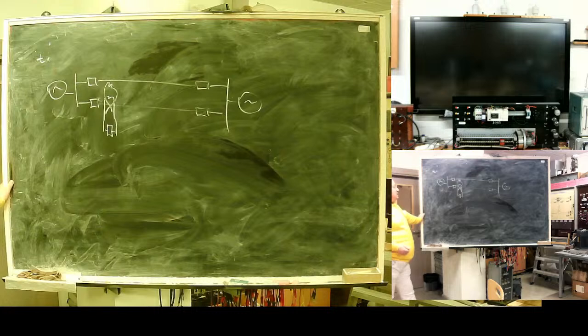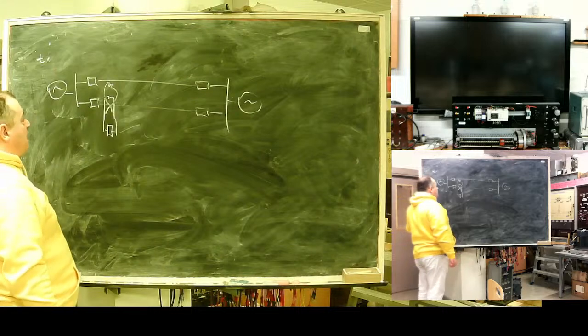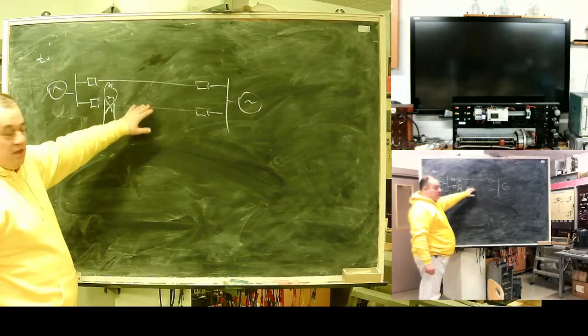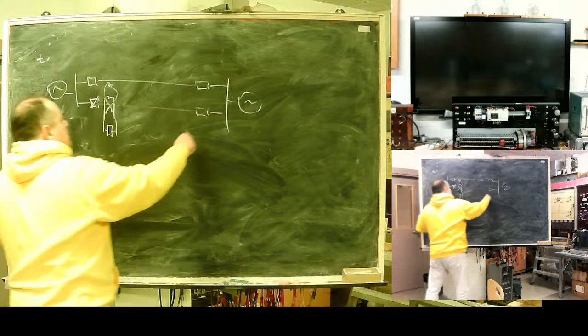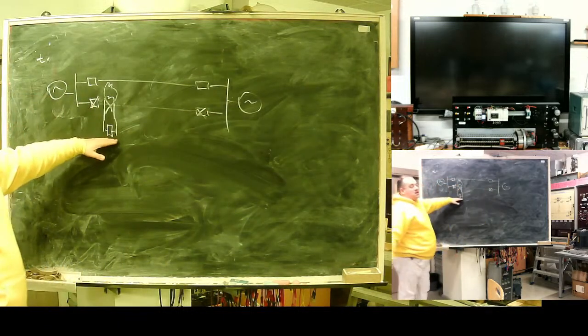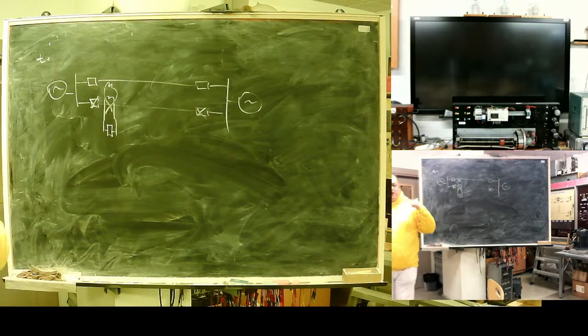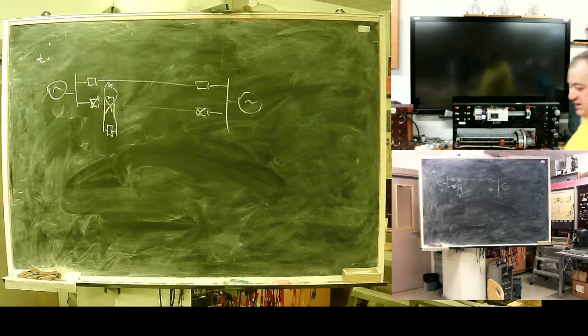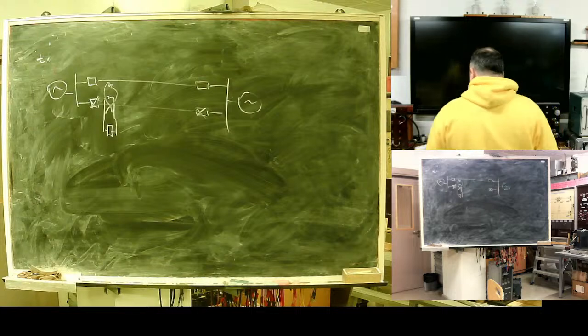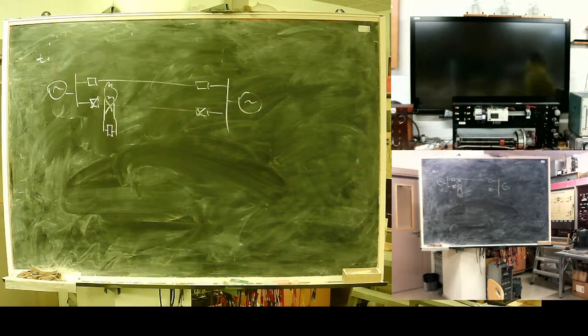Why do I hate it? Because it's a trap for human mistake. For example, we need to service this line. What do we do? We disconnect the switch. Instantly, the operation current of the second line trips this relay. So, this protection should be disabled before the line is disconnected. I don't like this protection.